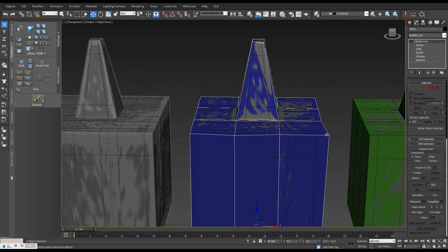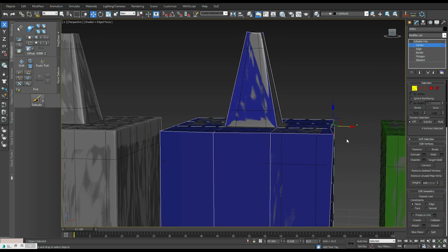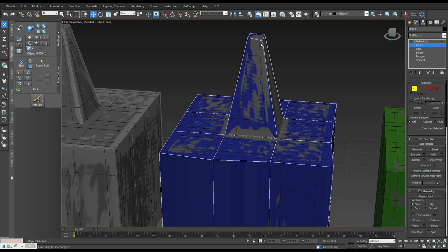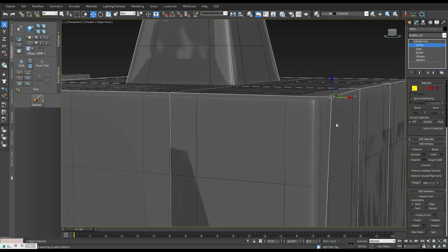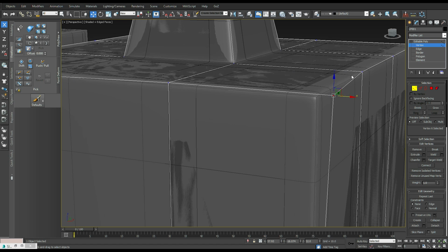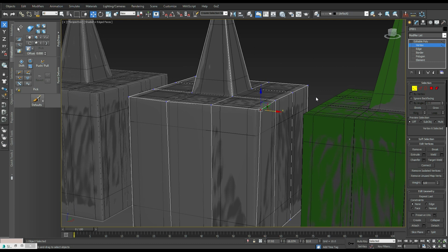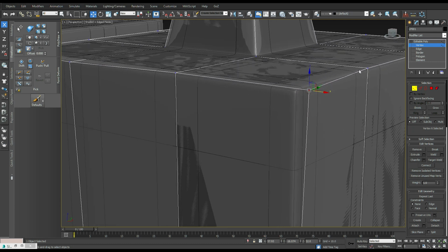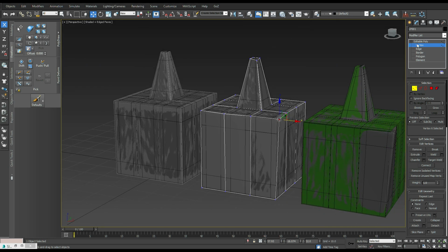The next one over here, I intentionally bent up and skewed up the low poly to show you an example of, let's say we already had our high poly set up and we're building our low, and I was a little quick with it or whatever, and things aren't lining up. In a situation like this, we're actually not going to record down that smooth transition in the proper location. Even though your bake will turn out and there won't be any technical errors with it, the actual location of that smooth edge transition won't be recorded down in the proper spot, as opposed to right over here. So if, let me grab both of these.